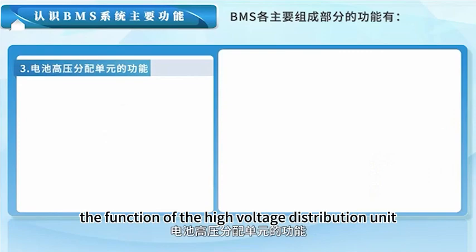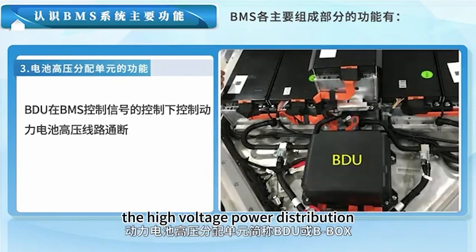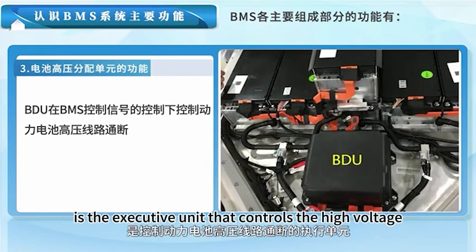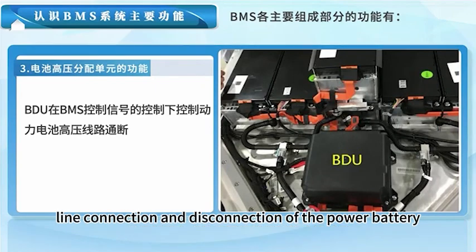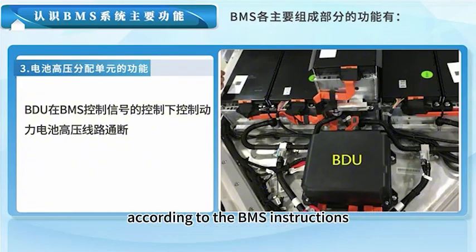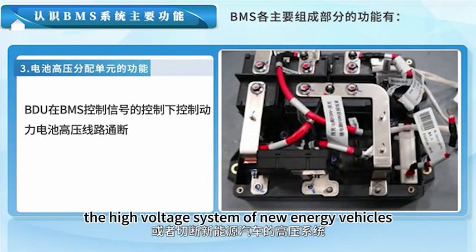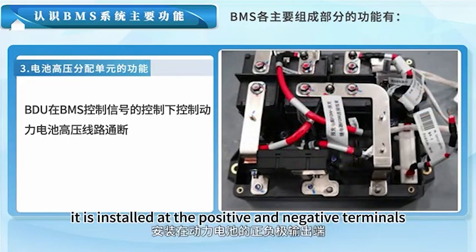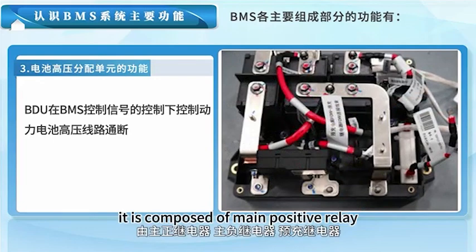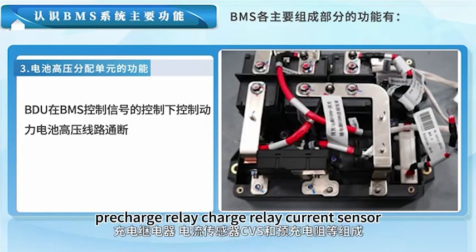The function of the High Voltage Distribution Unit. The High Voltage Power Distribution Unit of the power battery, abbreviated BDU or BBOX, is the executive unit that controls the high voltage line connection and disconnection of the power battery under the control of the BMS control signal. According to the BMS instructions, it connects or disconnects the high voltage system of new energy vehicles. It is installed at the positive and negative terminals of the battery. It is composed of the main positive relay, main negative relay, pre-charge relay, current sensor, and pre-charge resistors.